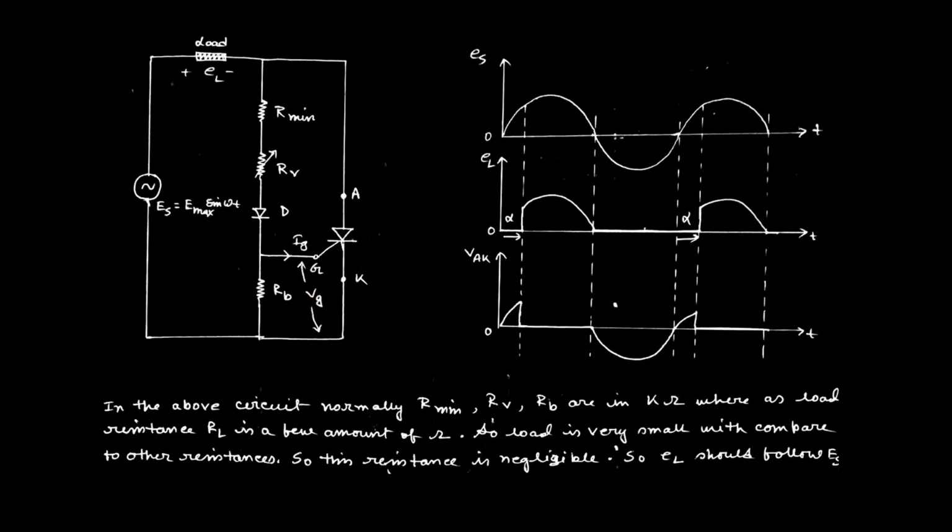It can be defined by a simple expression using the voltage dividing law, and I think it is known by everyone. In the voltage dividing law, whenever we calculate the voltage across any load resistance, it is equal to the supply voltage multiplied by that load resistance divided by the total loop resistance, right? The same thing applies in this case.